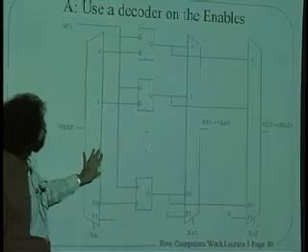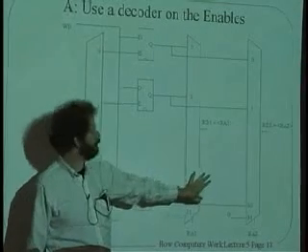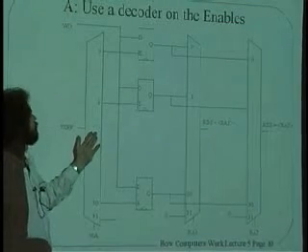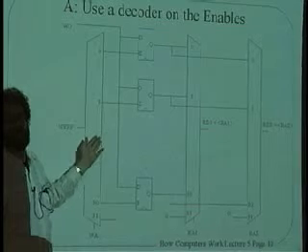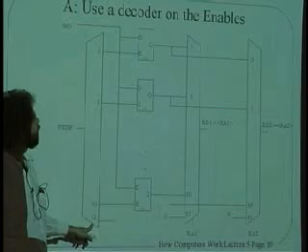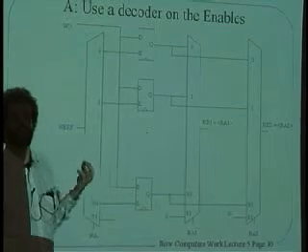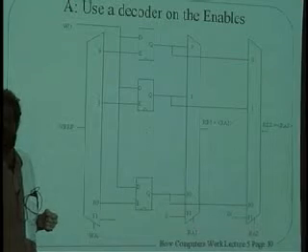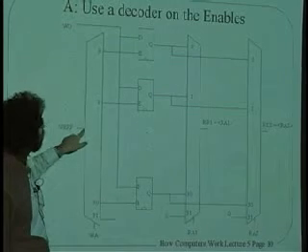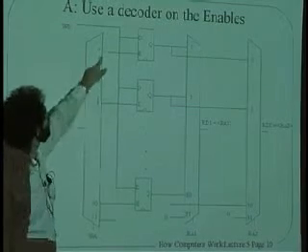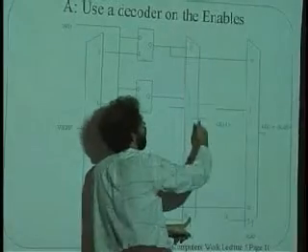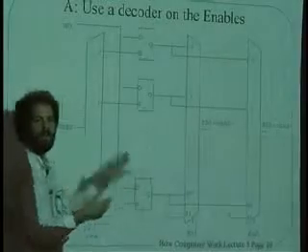And this device over here looks just like this one over here, except this is a selector, and this is kind of the mirror image of that. And guess what this is called? This is called a decoder. Okay, and what it does is it decodes an input here, which is 5 bits wide, and it figures out which combination of 5 bits those are, of the 32 possible combinations there are. And if the combination is 0, it steers this signal over here up to 0, in the same way that if RA1 is 0, it steered the 0 over here all the way down to here. So it kind of works the same way, but backwards.